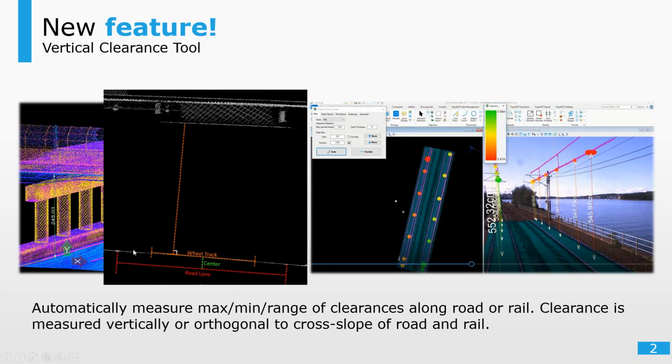For example, the manual approach from some other software was finding maybe a 2x2 foot plane here and a 2x2 foot plane here. As we looked at it, that's not really what the elevation is. This could be a rut or something like that, which will throw it all off. You weren't getting the right measurement. So we think just two points here and here with a line in between them actually tells us what our angle is. Then we measure that angle from the point cloud on top to the point cloud on the bottom, not the line, the point cloud. So we give you all those measurements.